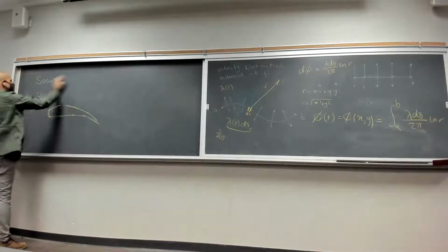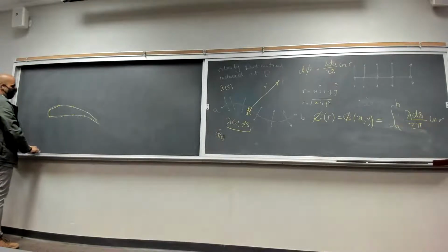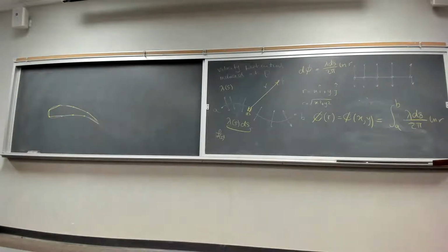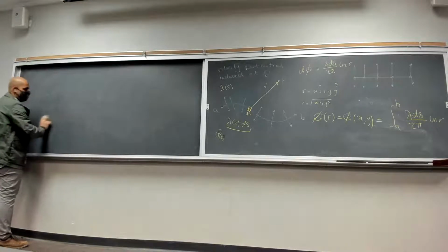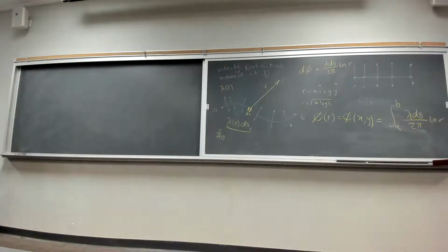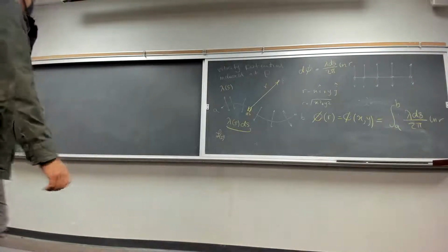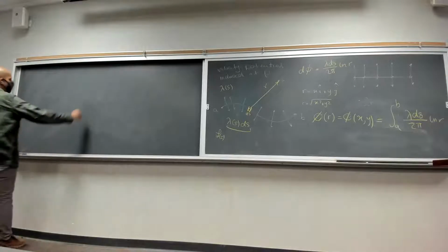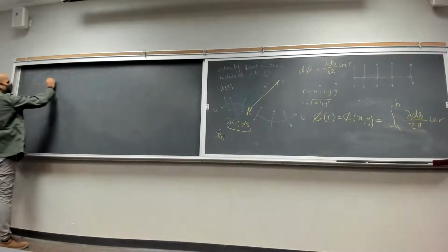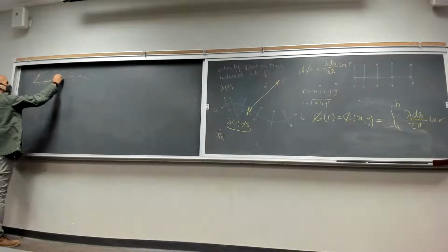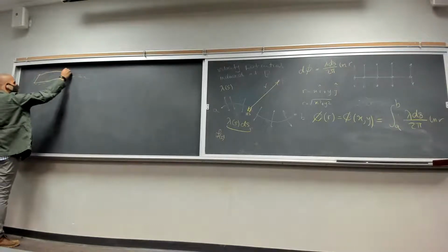As long as you can define a source sheet that can resemble the shape of this airfoil, you should be able to calculate that integral, right? But the idea here is that we cannot find this type of source sheet, right? We want to make it simpler. So I'm going to draw this again here. We are going to divide our system into different panels.